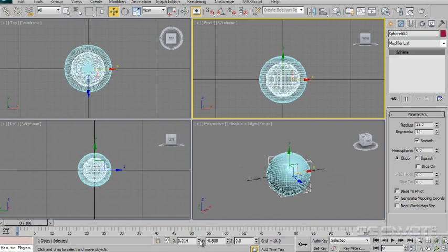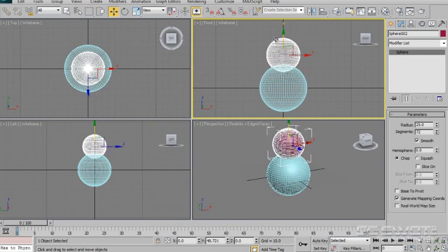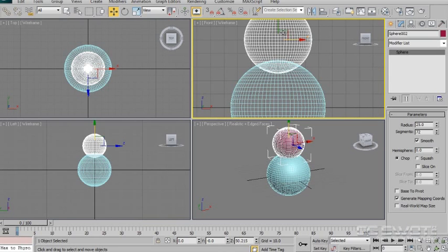So what we'll do is right click on the spinners, and anytime you right click a spinner in 3D Studio Max, you reset its value to 0, which is a really handy tip. So right click these spinners, and we now have a sphere that is perfectly sitting at world 0 like the larger sphere. Now in the front view, let's drag that up until they sort of penetrate one another at the base here.